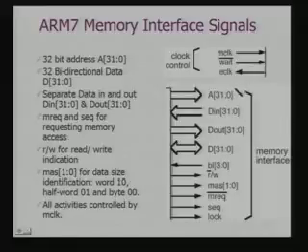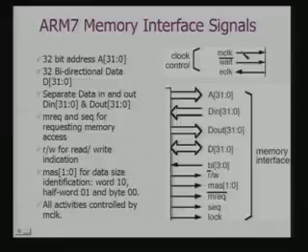Here you can find that the clock control has an associated signal called wait bar. This is an active low signal. In fact, your internal clock for the processor core is a combination of the two. And how and where to use this wait signal? If you remember, I said that in many cases my memory may be slow. When my memory is slow, the processor has to wait for a memory access. So the memory module has to tell the processor to please wait till it provides the data. In that case, this wait signal becomes important. That is why your internal clocking or internal operation is controlled through a combination of MCLK and the wait signal.